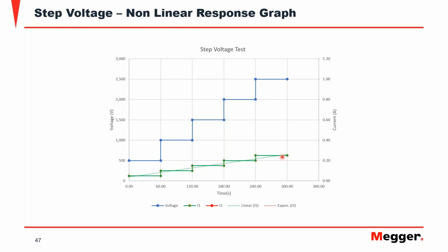If we increase the voltage, the current should increase in the same amount in order to keep the resistance constant. But if after some point in the voltage increase the current increases more than what we increase the voltage, then that means that the resistance is dropping after some point.